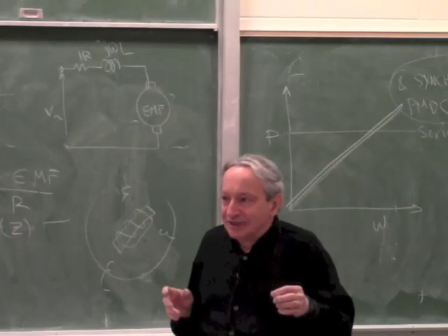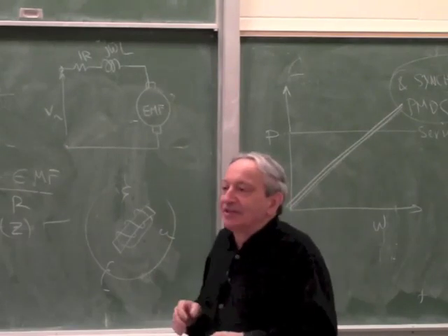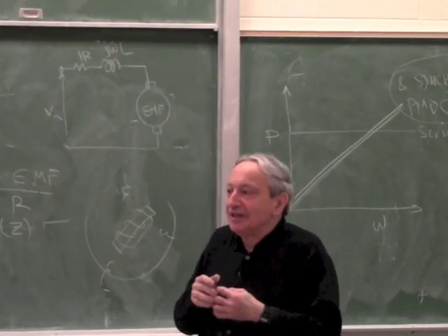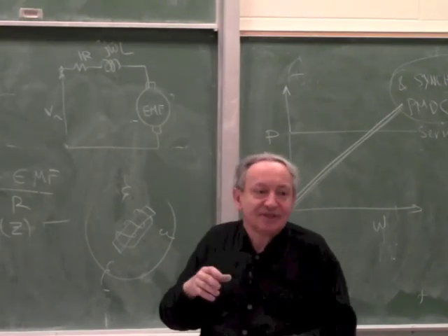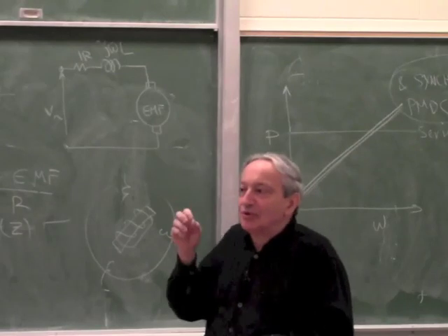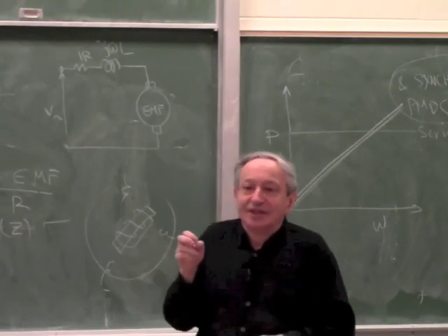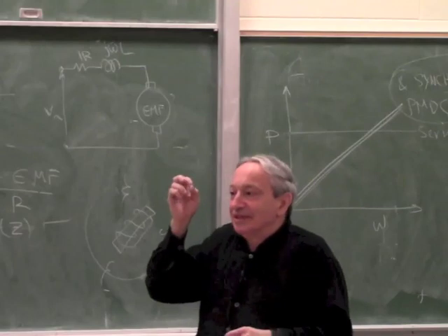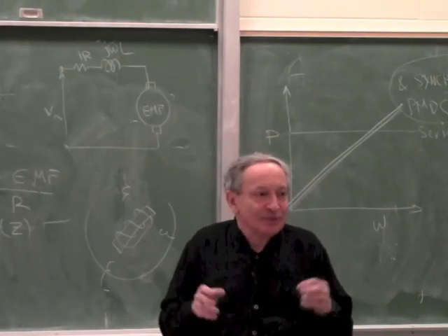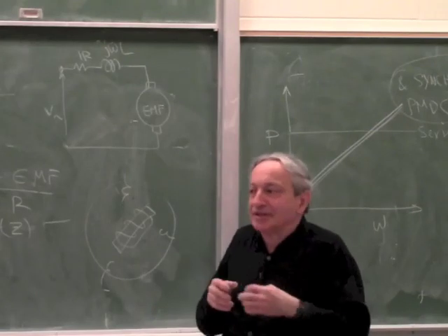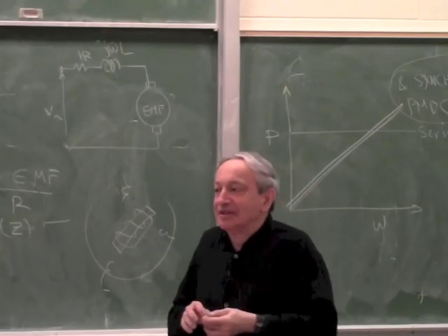RFI, right, it sends a lot of electrical interference, and it wears out, mechanically and from erosion. Mechanically it wears out just from wear on the brushes, but also it erodes, because each time you have a spark, it actually vaporizes a sub-micron amount of copper and graphite. So eventually the combination of the mechanical wear and the sparking will erode and need maintenance.